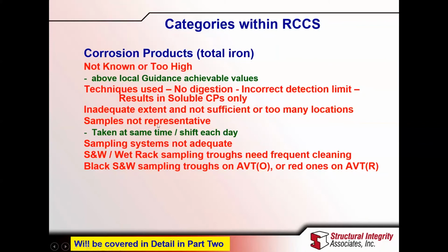Samples are sometimes not representative, and the biggest issue there is that the chemists or the technicians or the operating people take the samples at the same time of the day or the shift each day, rather than taking them when the unit is under the same condition.